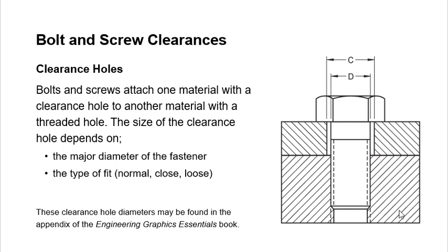You know that this is one material and that is one material. I would say part, different part. The material is the same thing anyway. By looking at the section type of lines, you know what that is. We are in cast iron here. So anyways, you have two different parts, part one here and two here, and this is joining the two, mating. So here is your clearance hole, and then you also have another threaded hole right there.